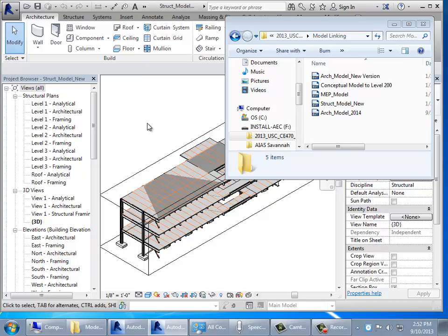What I'll typically do is I'll go through and it's house A, and I'll save the new version house B, house C. The problem with doing it that way is if you have a linked file, every time you change that name, it's going through and breaking the link. At that point, they keep on giving it a new name.